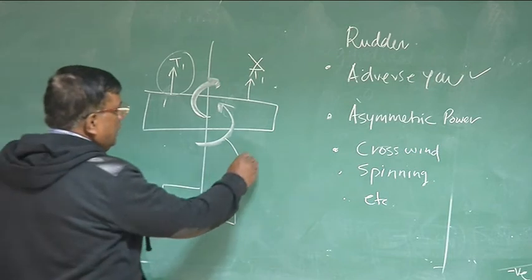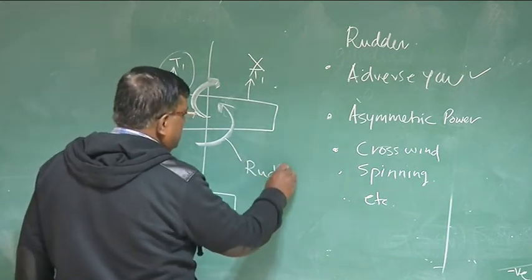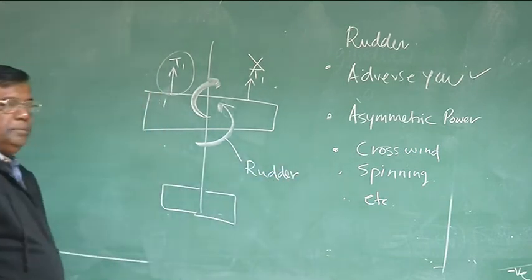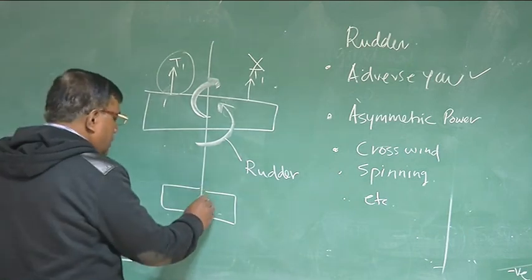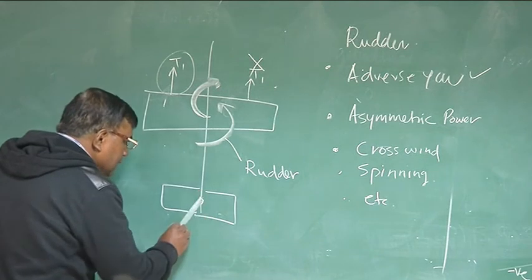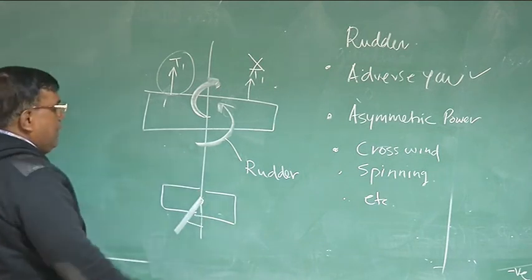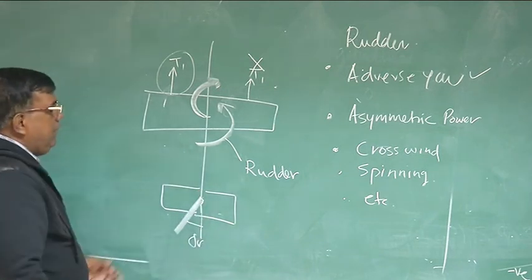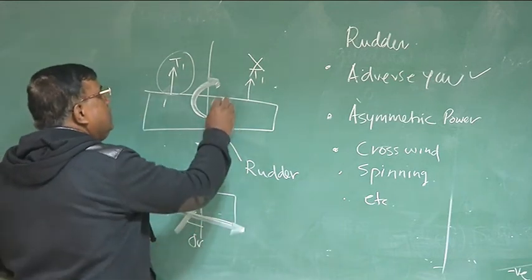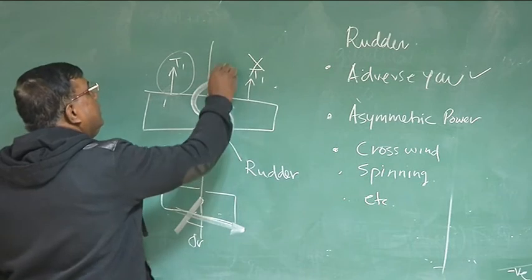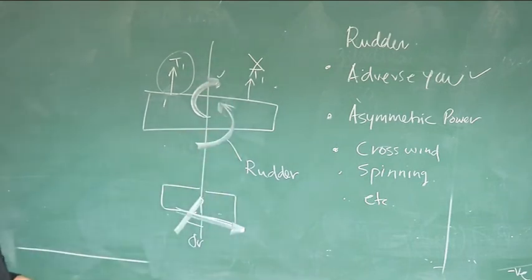This is through a rudder, by appropriately deflecting it. Okay? Which way should I deflect? I should deflect the rudder, you know by now, like this. This is rudder positive. If I deflect like this, it will generate a force in this direction, so that will give this moment which is required to nullify this moment. So rudder is extremely important. So rudder control power should be assessed.